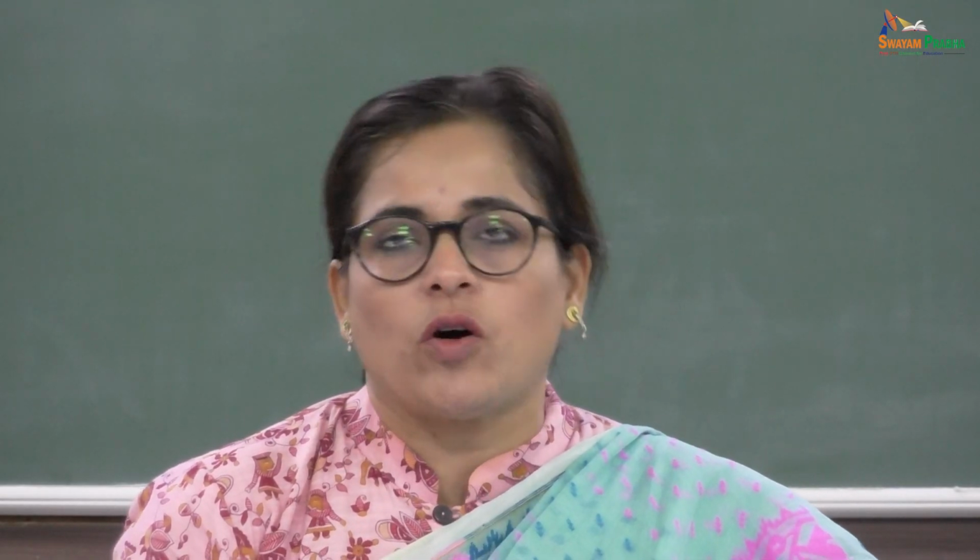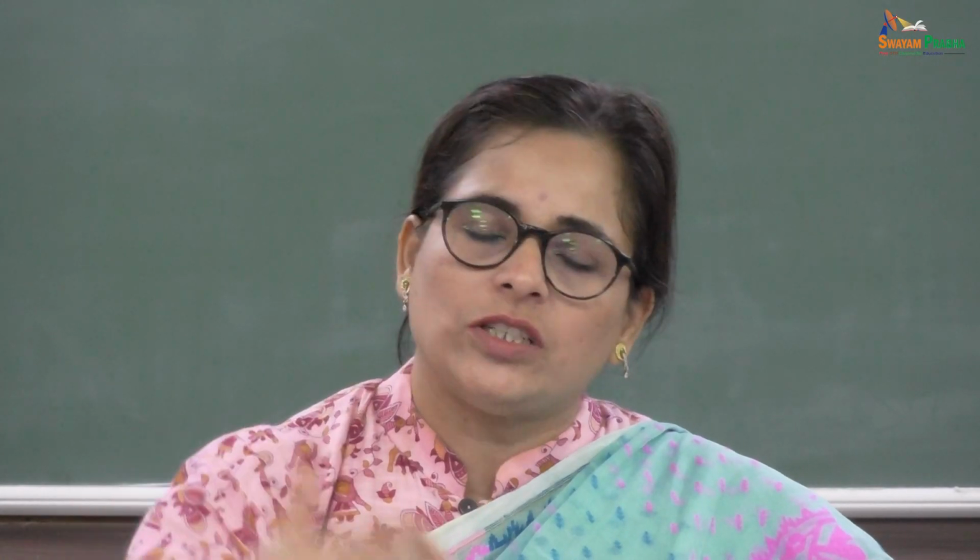Well, come to think of it, not too far back, right? So the point is that we did all these things. We're trying to figure out what is production, what is viscous dissipation. So we spoke about these things, looked at pictures, and said, oh, there are big eddies, so they become smaller. There is an energy cascade. When the energy enters the flow field, where does it enter? It enters into these eddies, which are the largest in size.